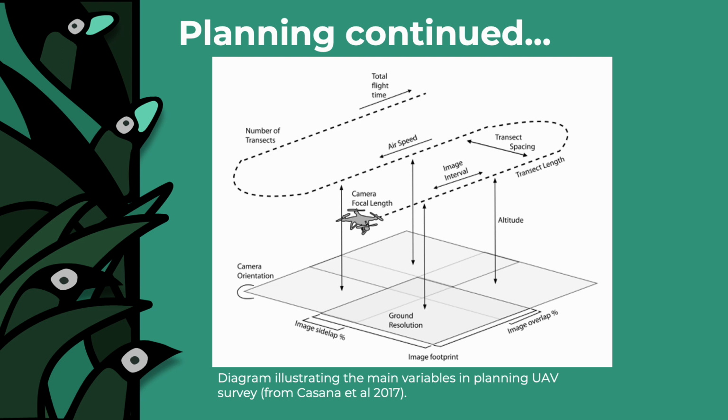The optimal flight elevation is dependent upon the preferred image resolution, the coverage area, and potential objects that might be hazardous to the UAV. Selecting flight elevation reflects a balance of considerations. Lower elevation flights generate high resolution images but require more photographs to achieve the required coverage.